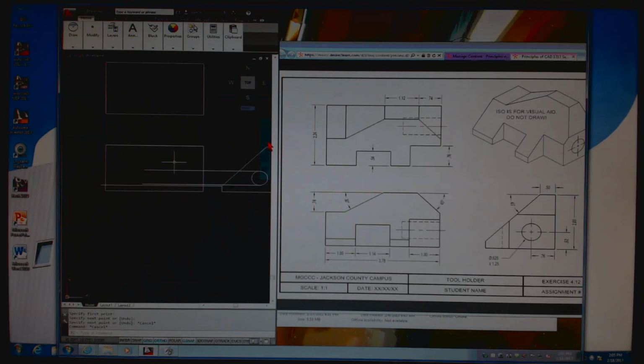Thing you'll learn real quick is the front view, right side view, both share what? What are we getting from the right side and the front side? Just by looking at those images. Height. Are we not? This tells me how tall that little piece is, right? So if I project it straight across, it has to line up. It has to be the same exact height.